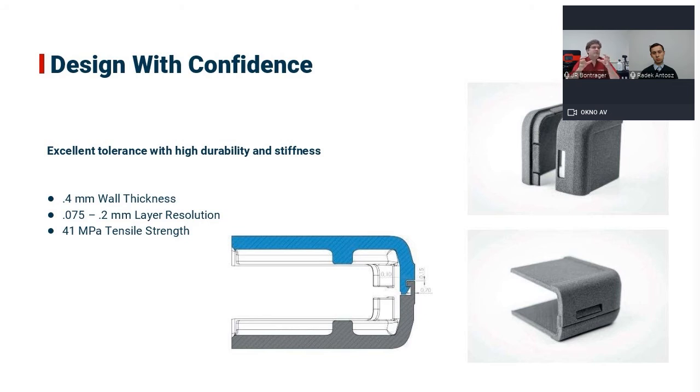And not to mention, your base tensile strength for your PA12 nylon is pretty good compared to most other things in the business, without having to injection mold it and spend that kind of money to run tests. SLS is very, very good at this.